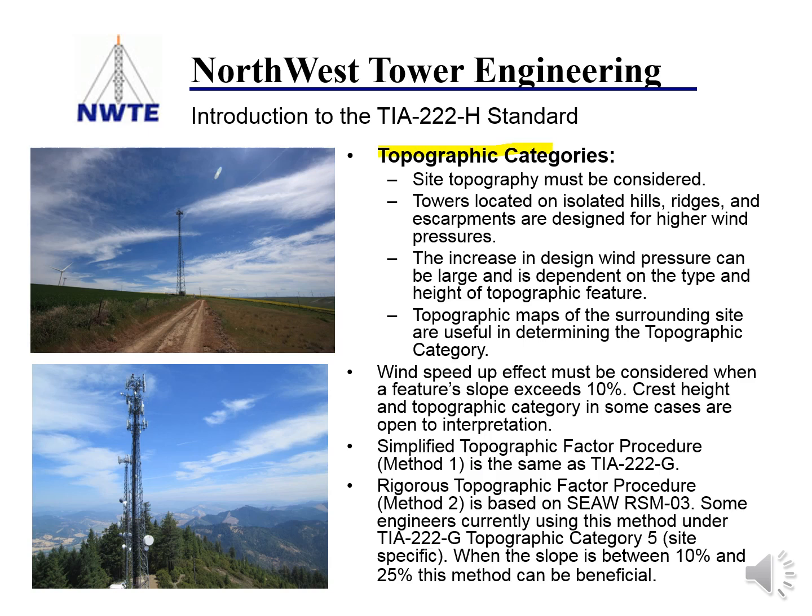Okay, topographic category. This is in reference to hills and the speed-up effect that we see when we're on a hilltop. Speed-up effects must be considered when a feature slope exceeds 10%. So 10% is not particularly steep.